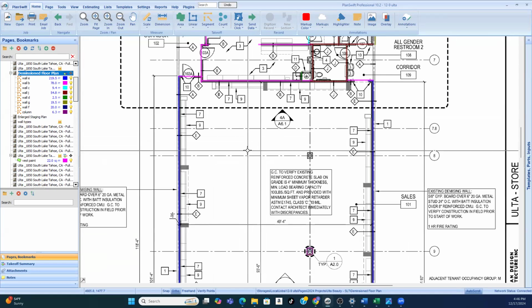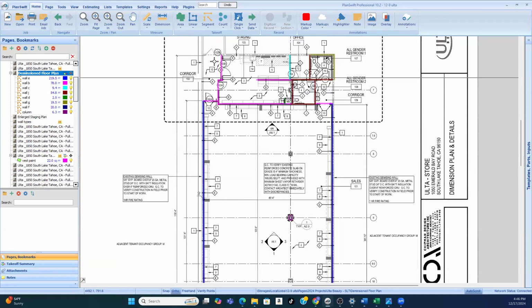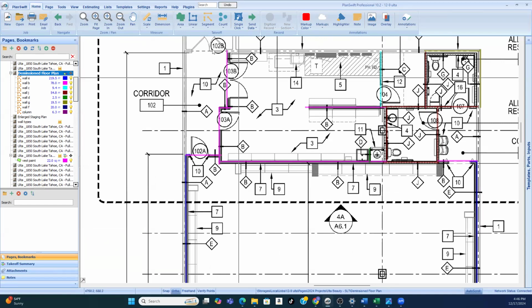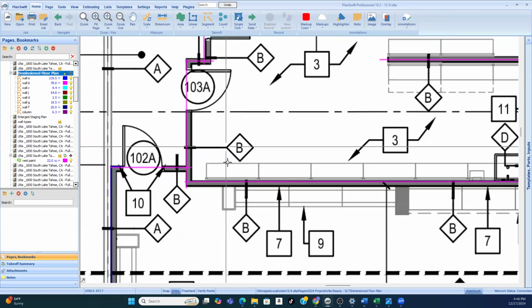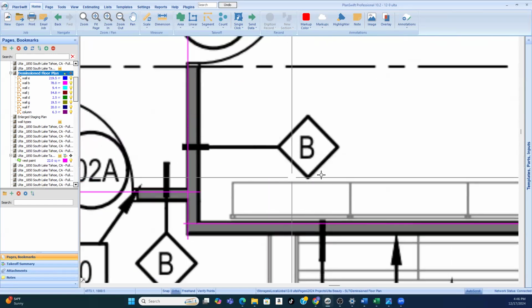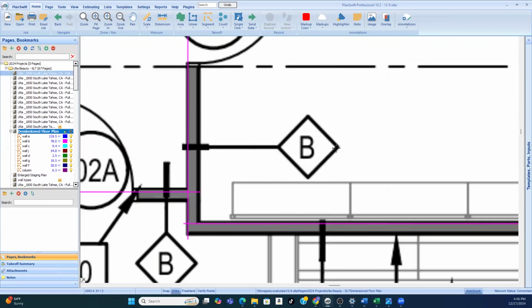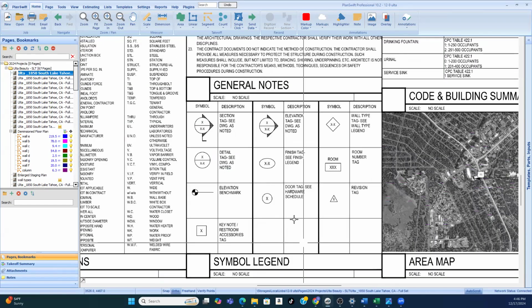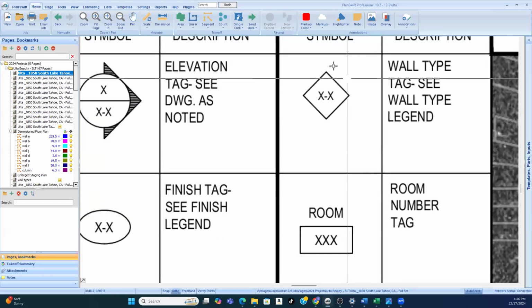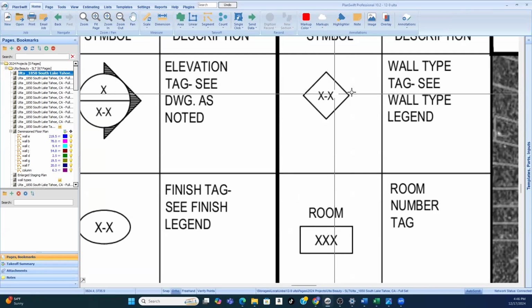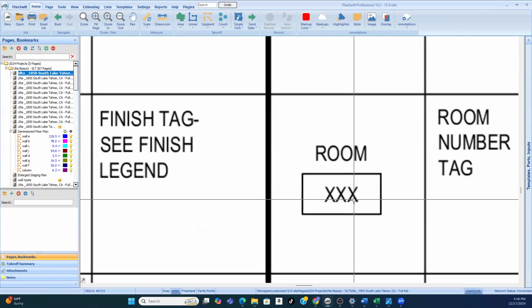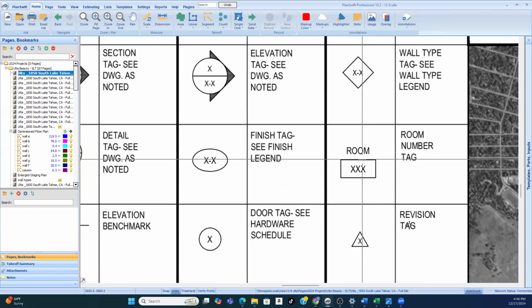This is the plan that's going to tell me all about the new walls from the ground up. And so I'm going to assume I'm going to have wall tags all throughout the new building, which I do. And in the wall schedule, we have B walls, and we see that this symbol is associated with the walls. If we look on the cover sheet, you have the small basic symbols. The sideways square is the symbol they're using to tell me that these are walls, wall tags. And then the room tag, they're using that symbol.